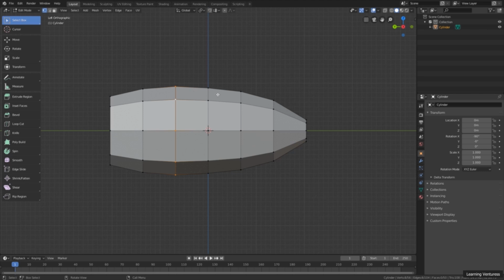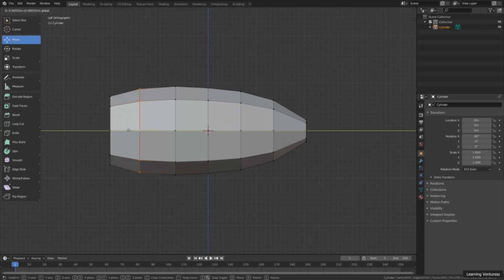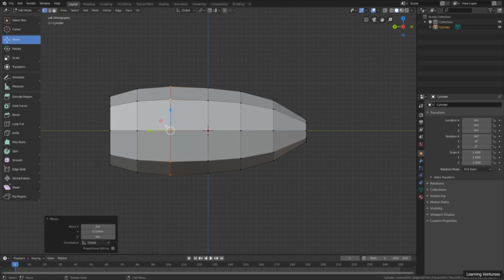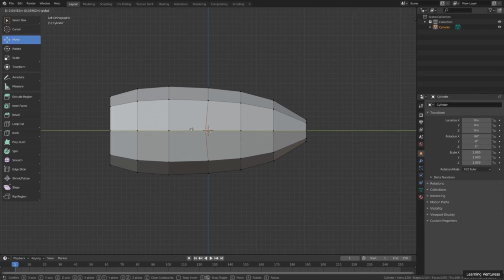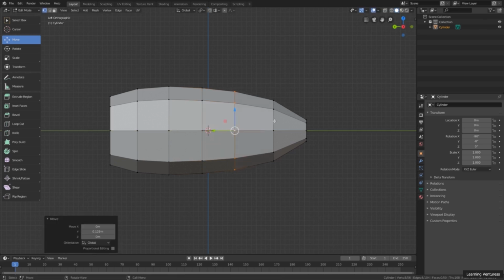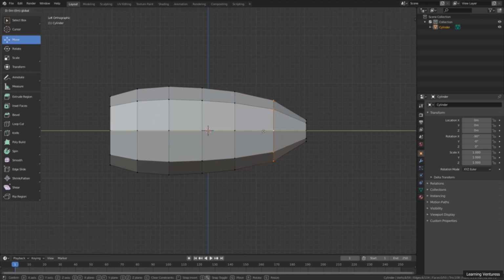And I'm going to move them a bit forward so that the cabin is created more to the front of the airplane. So they are going to be created from these polygons here, and so that the cabin is created more to the front, I'm going to move all the loops one by one by selecting the loop with the Alt key and move the loop forward in the Y-axis using the Move tool. So just clicking the loop with the Alt key pressed, and with the Move tool, move the loop a bit forward, like this.